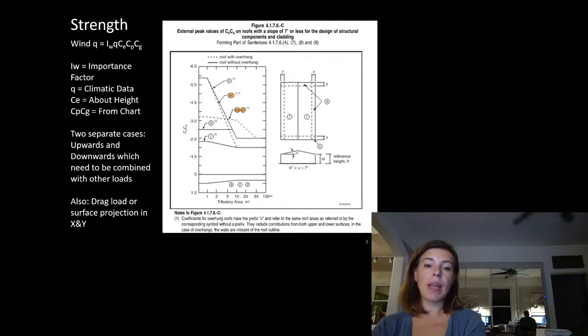If we have something slightly more rigorous, or built in a place that is very wind governed, the Australian code has a really good open structures wind clause. That's where you go, right? That's where I go. Or have you changed where you go? Yeah, ASCE 7, for open structures. For open structures, yeah. So we used to go to the Australian code.